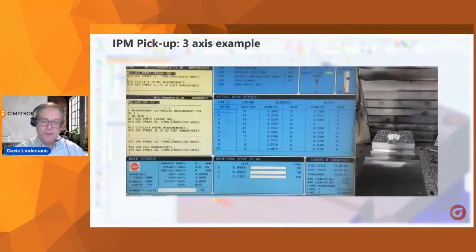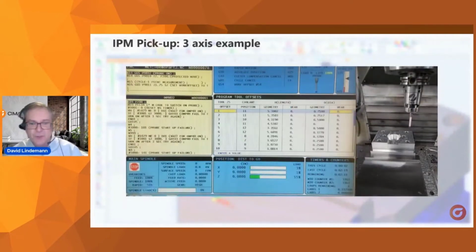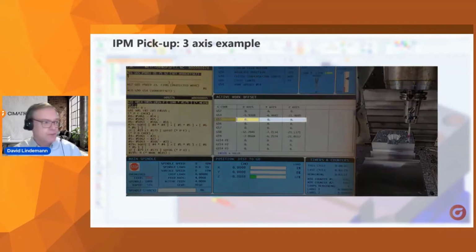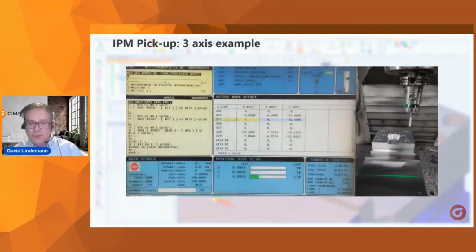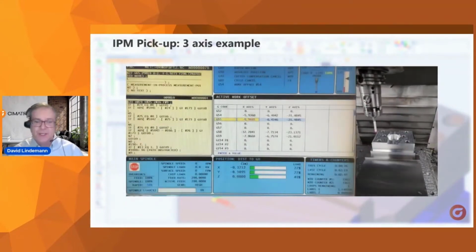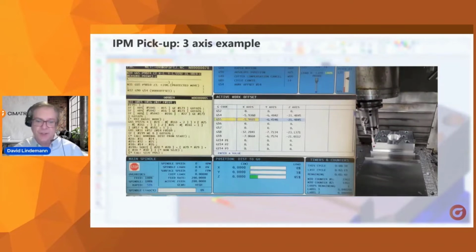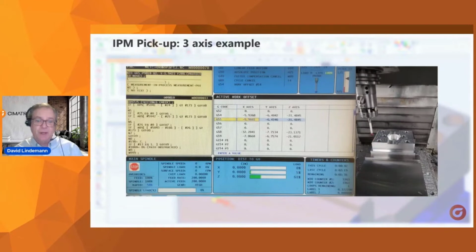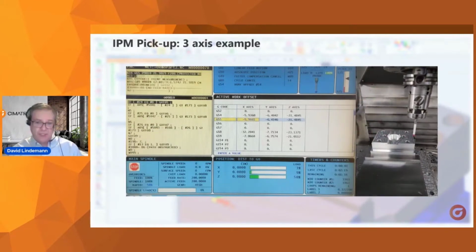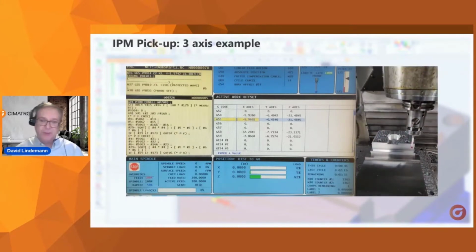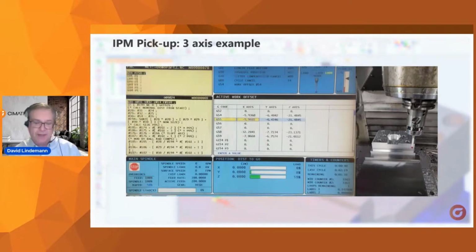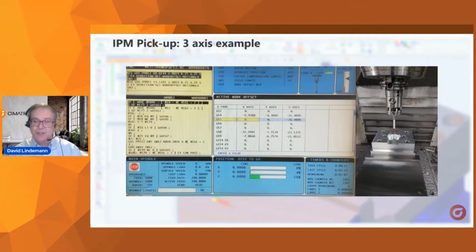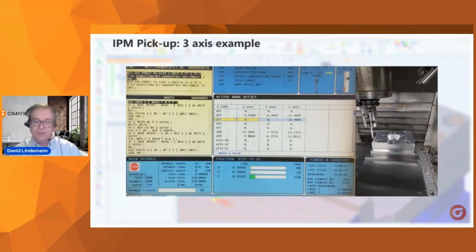So now going forward, let's look at that on the machine. As you watch the controller, you'll see in our work offset page, we zeroed out G55. And as the probe does its thing, you'll see how it's putting that information into that work offset. So very quickly, we can get a much more accurate pickup than normally we would using the conventional tools that we may have. And then we'll come across again here to the opposite side.